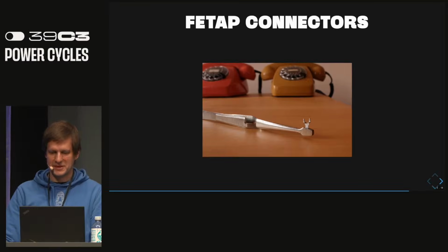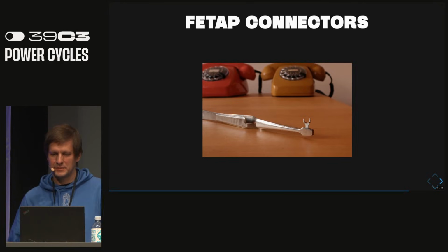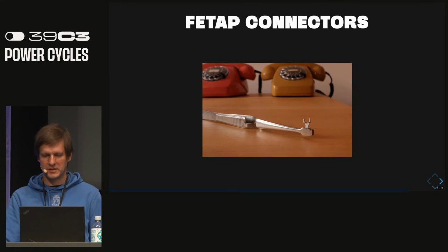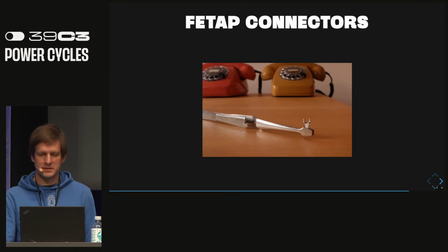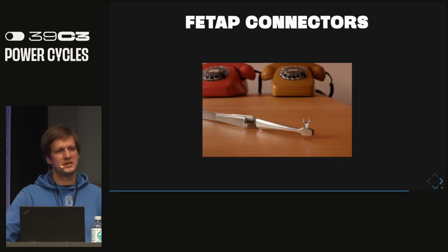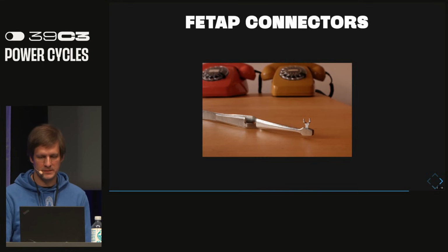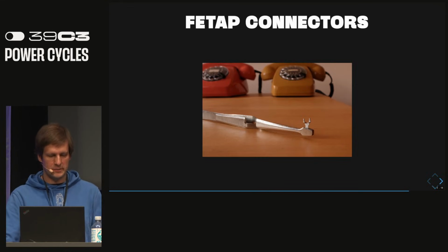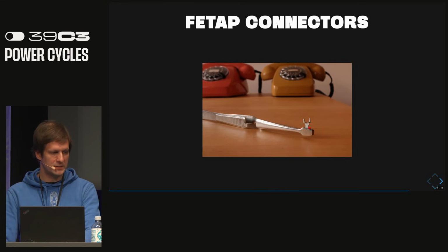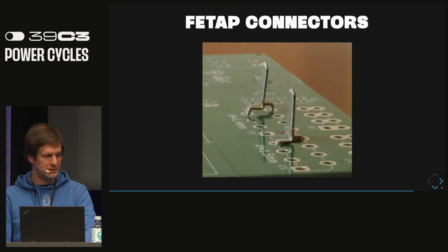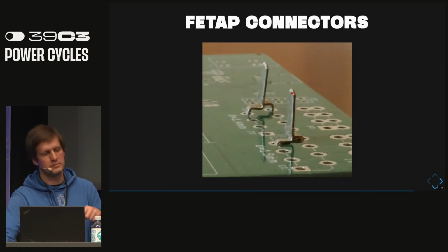Okay, the last challenge I was facing is, since version 2 shall be really pretty, I wanted to use the original connectors, not improvise too much. And these connectors and the hook switch as well are not produced anymore, so I desoldered them from the actual old PCBs. And here you see one peculiarity. You see a cascaded pin outline, and basically the thicker part shall be pressed into a hole and remain in the hole, as you see here, and the thinner part is supposed to be soldered.